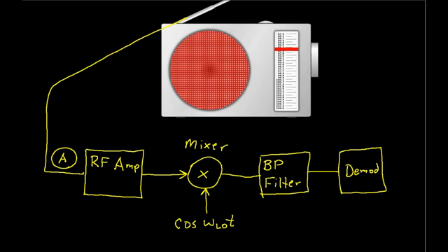If we go back to our diagram of the AM receiver, the RF amplifier takes the signals coming in from the antenna, and these signals can be very small sometimes, millivolts or less, and it amplifies them. And also it's a tunable bandpass filter, so it starts to attenuate the signals from the stations that I don't want. Attenuate means to be made smaller in magnitude.